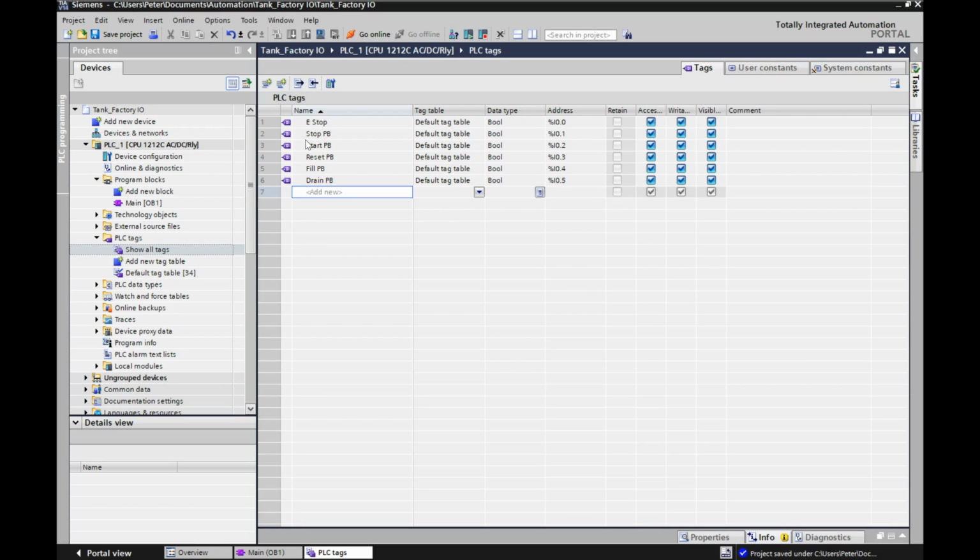Okay, next one is my auto switch. Remember that I said in the previous video that I have both an auto and a manual. So you'll see that auto and manual are going into two different inputs here. So I input 06 and input 07 for my auto and my manual. If you're low on inputs though, you can always just use one of those guys, right? Because it's not going to be auto and manual at the same time. So you can use one switch and use the opposite. Like if you're using a normally open for one, you can use a normally closed for the other.